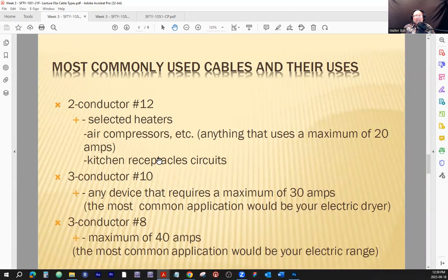If you want to up the ampacity, it's not enough just to replace the circuit breaker with a bigger one. You also have to consider the gauge of the wiring. Otherwise, you seriously can start a fire, because if you run more amps through the wire than it's designed for, it heats up pretty quick.